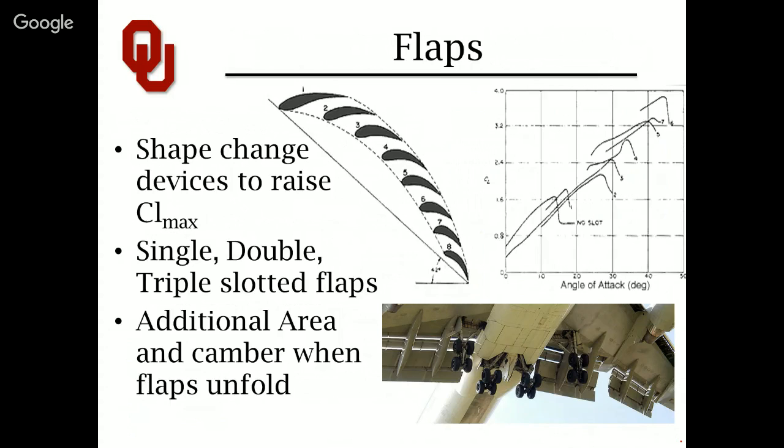This is an interesting study that I always like to introduce students to first when we discuss flaps, because, well, if airliners often have 2 or 3, would 4 be better? Would 5 slotted flaps be better than 4? Would 6 be better than 5? And here's your answer. It's all about pursuing higher and higher coefficients of lift. So you can see here on the right, this is the accompanying graph from the study shown at the left. They took a profile and started adding more and more and more airfoil shapes to it. They call it kind of the Venetian blind experiment, if you know that style of blind from a house or a window.